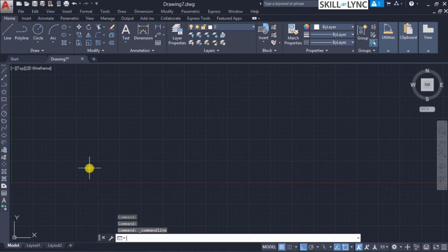Okay, so for quicker understanding, let me also bring in the command prompt to see the different option variants. The first requirement is the specification of the start point. Once that is done, you can see the next options. By default, it will start plotting a line, so it expects the next point. Whereas you can also see the additional options that you have. You can use the option of arc to continue the next point as a curvilinear element rather than a linear element.